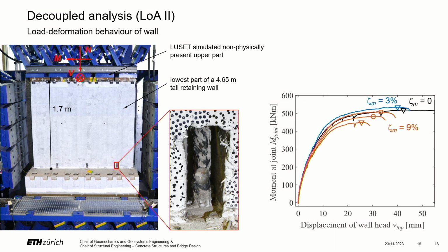So what is the difference? In this curve here, we had a specimen with 3 bars damaged to 30%, and in this specimen we had 6 bars which were damaged to 15% cross-section loss. So there obviously is a difference in the behavior, and it is influenced by the number of corroded reinforcing bars.